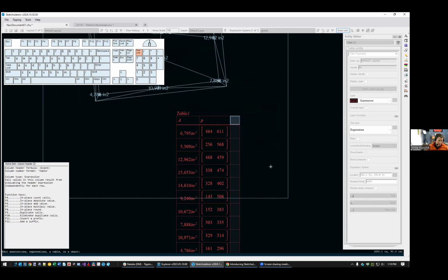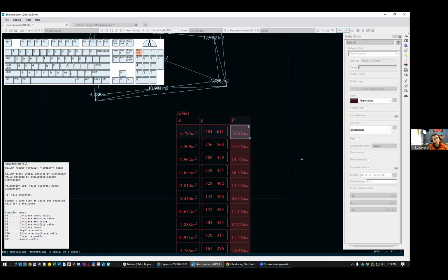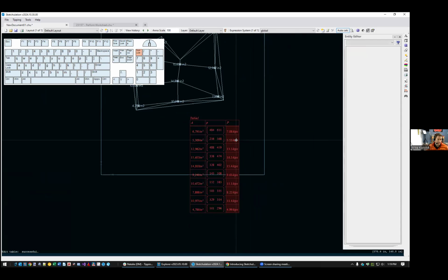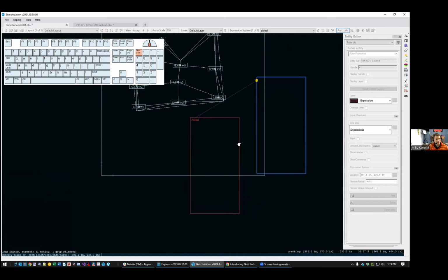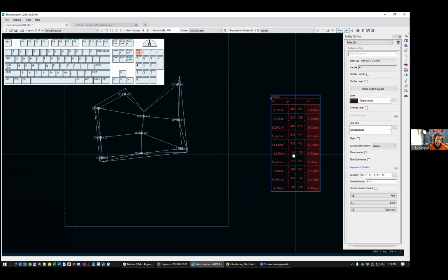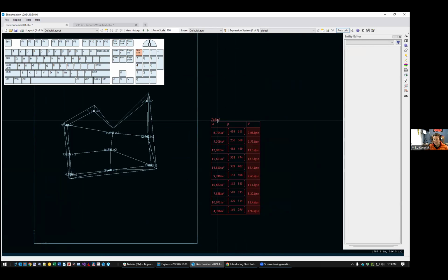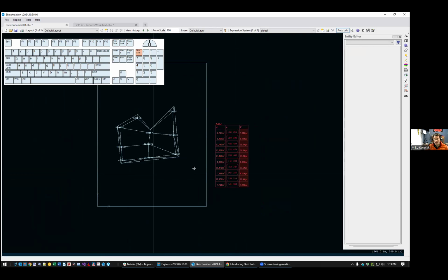Maybe, let's say the weight of your floor is 150 PSF, then your axial demand would be 150 PSF times A. And maybe you want to put that in kips like that. And so now you have some column loading that way. I might use this later as a little example for charting, but we'll leave off on that for now. Any questions on the review so far?